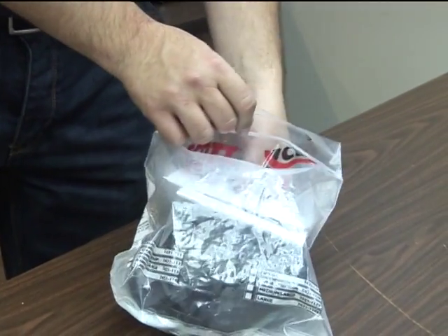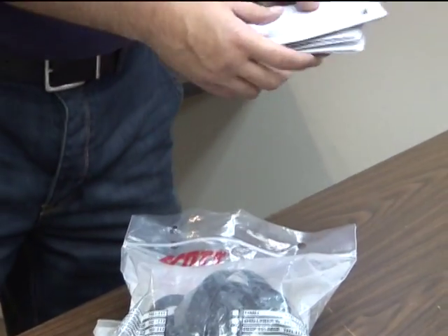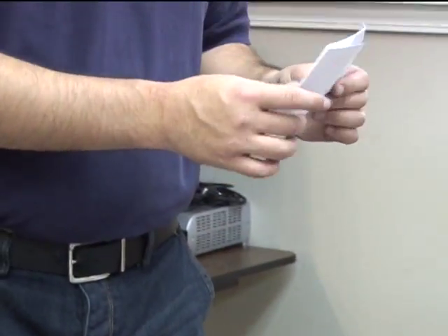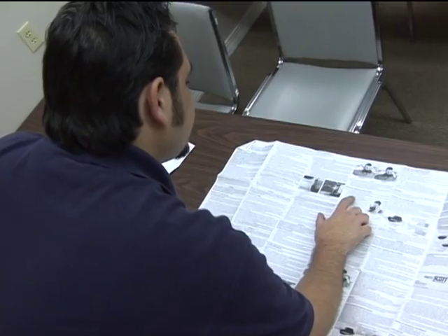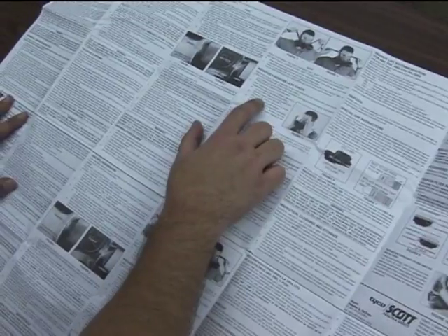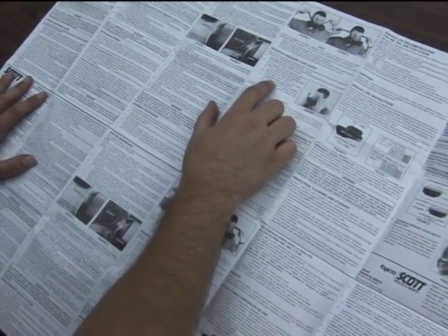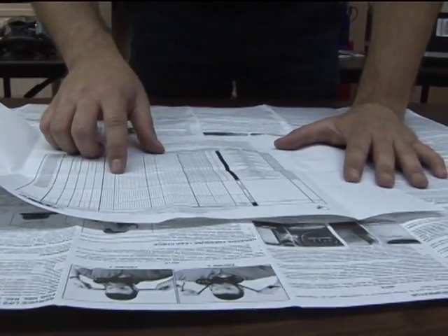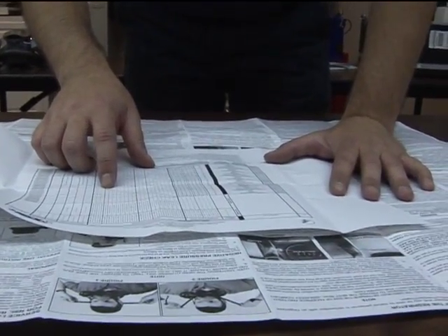All manufacturers of respirators provide recommended user seal check procedures with their instruction sheet. The respirator manufacturer's recommended procedures for performing a user seal check may be used instead of the positive and/or negative pressure check procedures provided by the employer, if the employer demonstrates the manufacturer's procedures are equally effective.